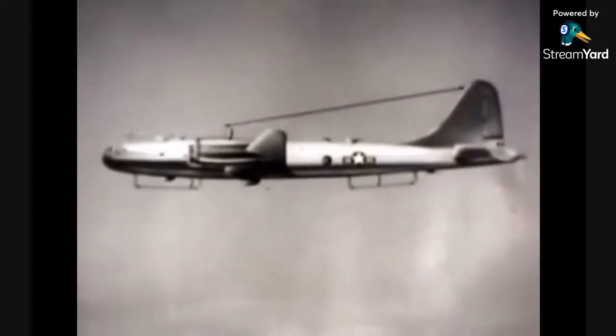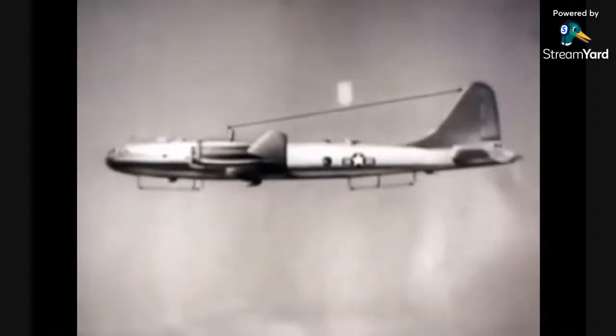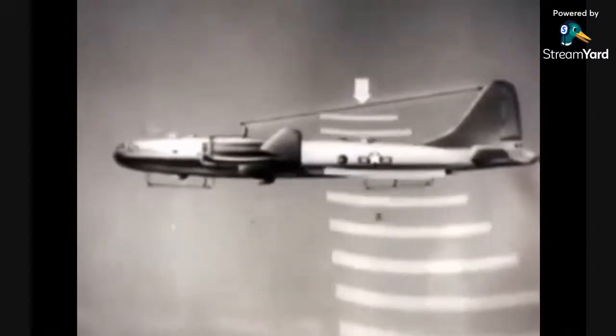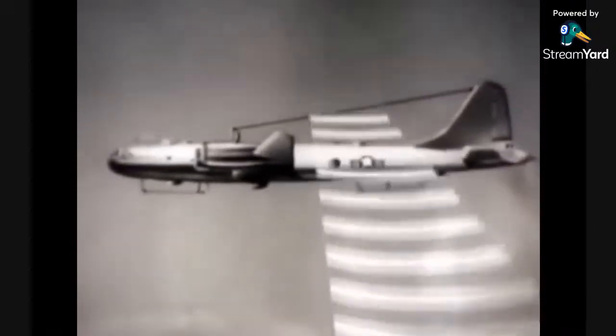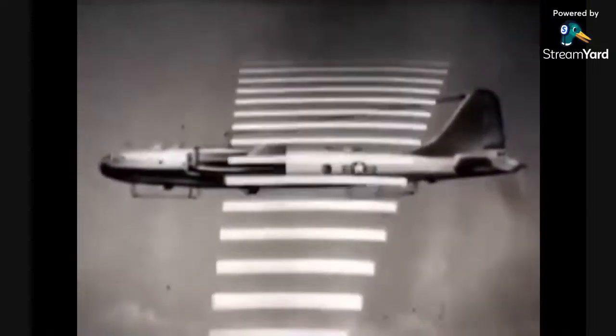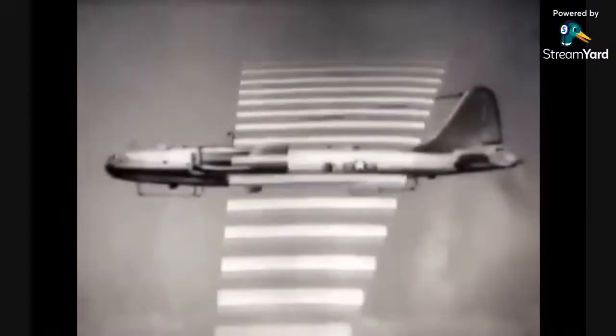Now, as you recall, while the command radio is basic for all aircraft, the liaison radio is also basic, but only for aircraft having a radio operator. A fixed wire extends generally from the stub mast to the vertical stabilizer. Its job is of course twofold: sending and receiving. As there's no way of knowing where the ground station is located, a non-directional system is necessary. And so with the exterior mounted antenna, the wave pattern resembles a very rough figure 8, as seen in a cross-sectional view.